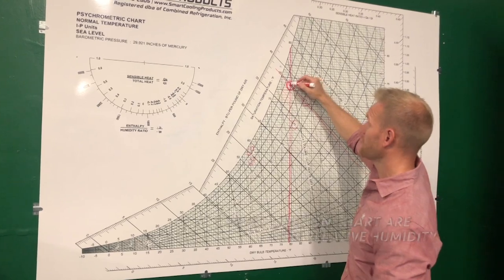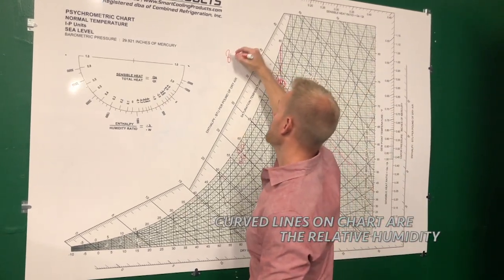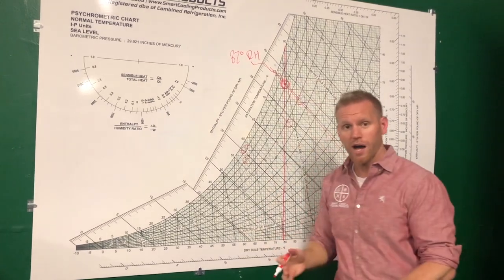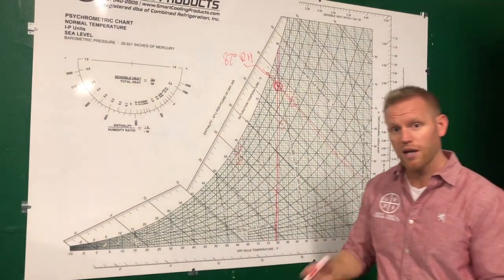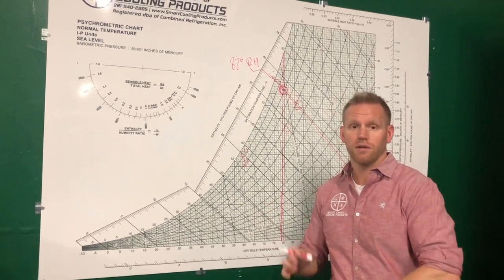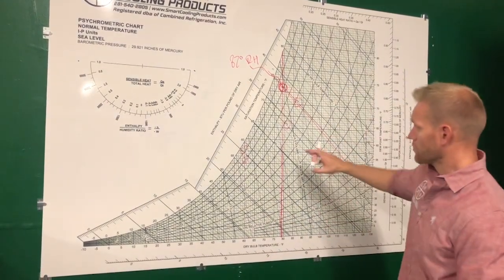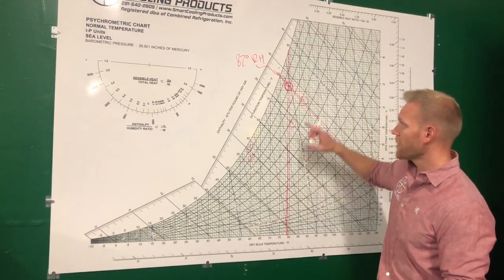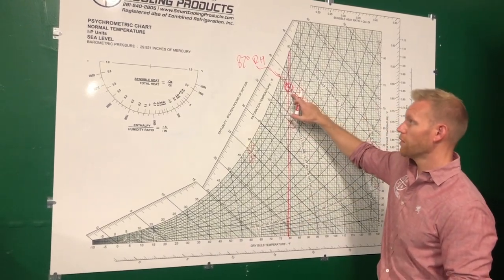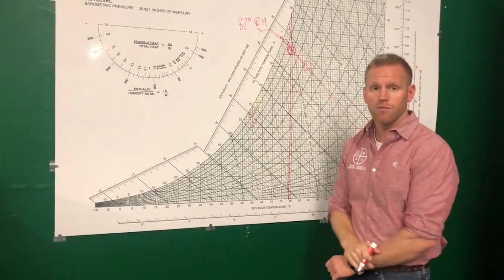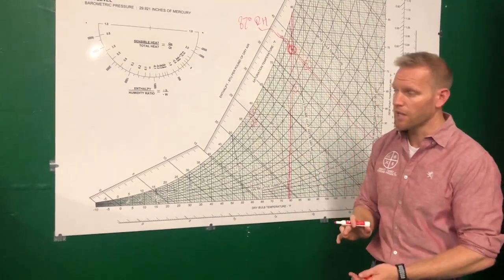I would say we're somewhere towards the 82% relative humidity level. Why? Well, it's Houston and it's been raining on and off, and so this is a shop space, so it can be fairly humid. Okay. So we can represent the same point by saying 79-degree dry bulb and 74.8-degree wet bulb, or 79-degree dry bulb at 82% relative humidity. We're saying the same thing.